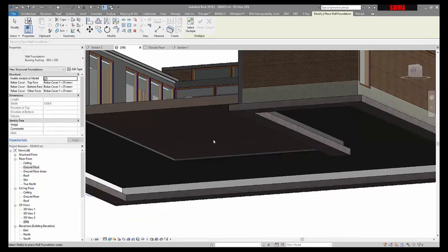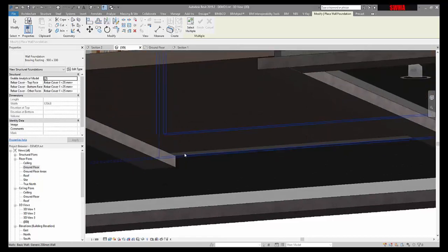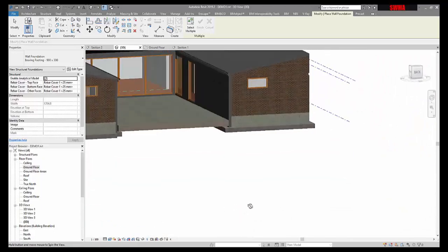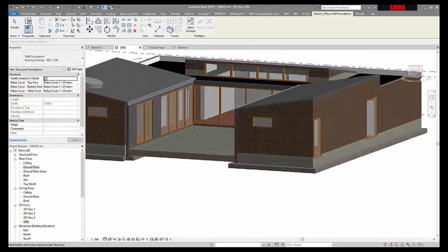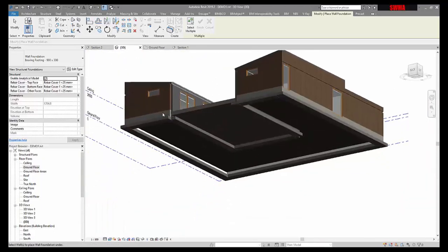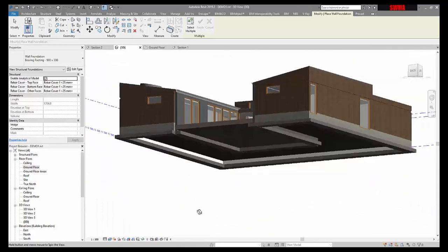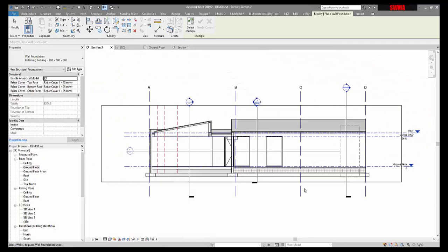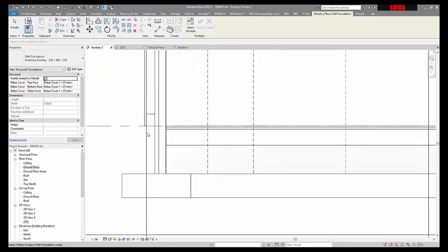You can see these ones here. Need to add just that. And that will now pick up the weight of the wall. Now it's just because I haven't done all the join conditions, but it's a really simple way to add some footings to your design here, and of course they're going to be showing in the section. So here we go, our block work, our brickwork above, the block work going a little bit above the actual ground level, and then all of this will be sitting underground.